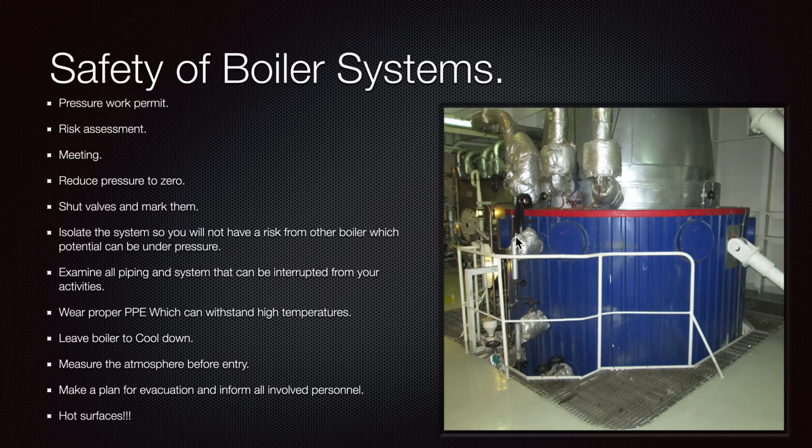So let's say, for example, we have the pressure gauge here. It shows 0. And on the checklist, also the question is: is equipment pressure 0? You say yes, because you see the pressure gauge. But later on, when you open that one, there is some pressure present. So that means that your pressure gauge probably had a damage or a problem, or the instrument is not functioning properly.